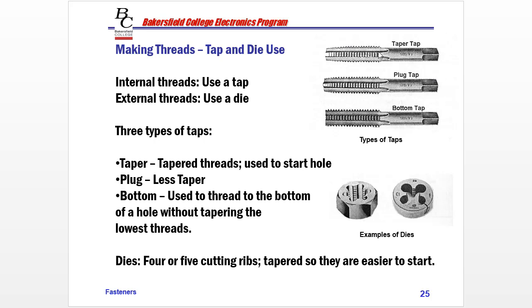And it would have the drill bit size to use for the proper thread diameter. Sometimes it's on the tap itself printed on the side, but most of the time it's the size and the threads, like 1/4 20 would be coarse, or 1/4 28 for a fine thread tap. So what we would do, we'd go to the chart. Sometimes it's on the inside cover of the case that holds these, and sometimes it's just a loose card.